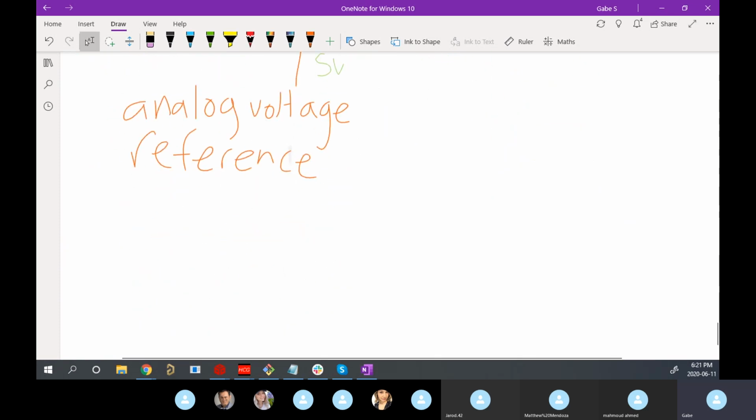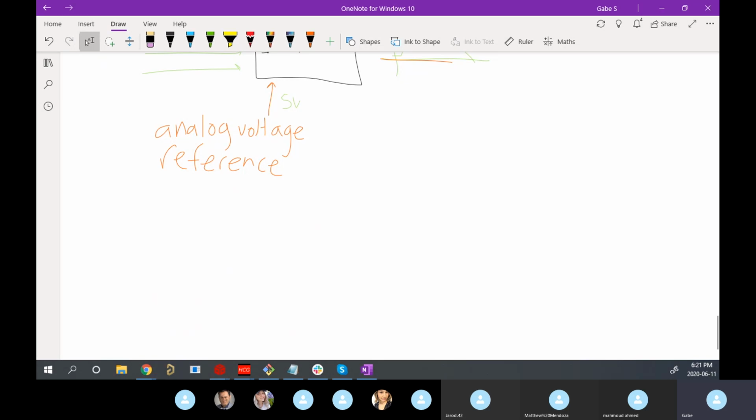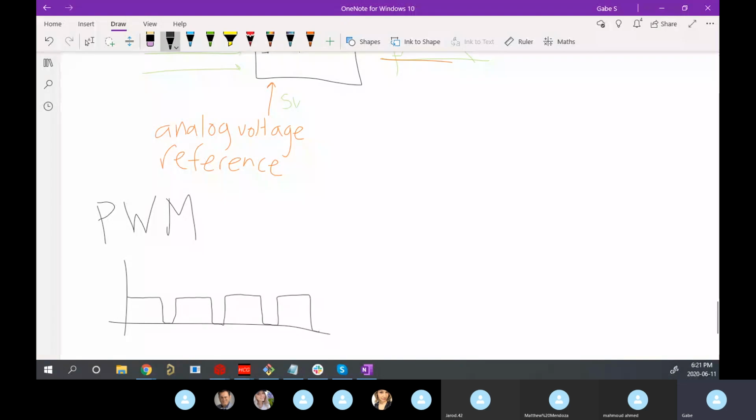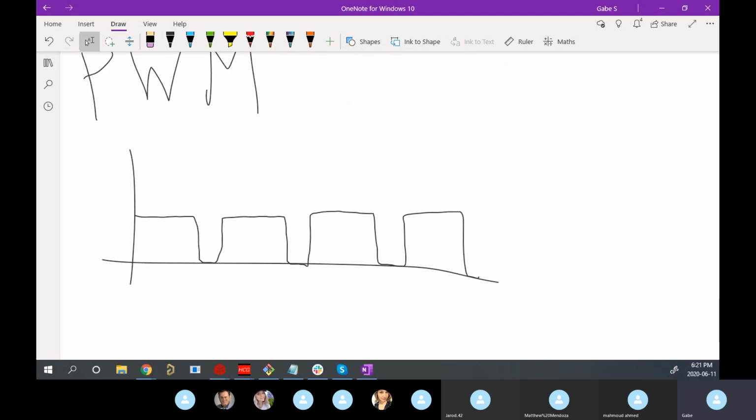We also talked really quickly about something called pulse width modulation, and we definitely didn't do it justice. But the idea is essentially using one signal and turning that on and off really quickly with different amounts of on time and off time within the same cycle, right? The general principle is that you can do this just with the GPIO, right? All you need is zeros and ones.